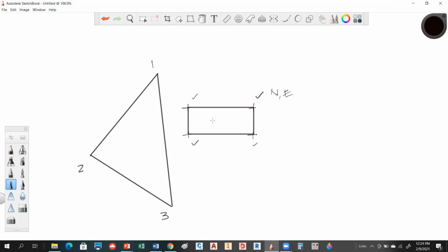So just remember the building at this point doesn't exist, but we have our control over here that is related to the same grid system, the same northing and easting system. So what this allows us to do is lay this out using my ground control. So what I would do is say, okay, I'm going to occupy 1, backsight 3.